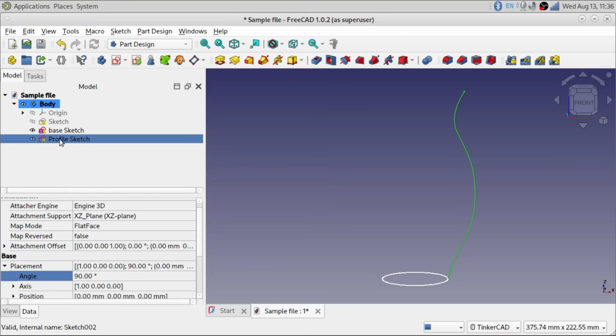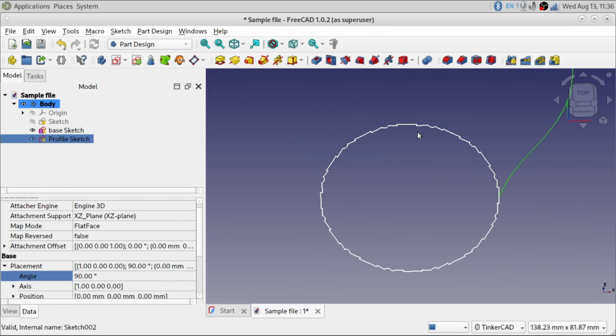I'm going to want to be able to tell it how far to rotate or twist the clones if I want to put a twist on the vase. And I'm going to want to give it a minimum rotation value for each sketch, because there's another issue with the additive loft, especially when you have a repeating pattern like this. Every 30 degrees I have a repeating pattern. If I rotate the next sketch more than about halfway, the additive loft is going to look for similar shapes and it'll snap back. It won't continue the twist, which is something I've learned.